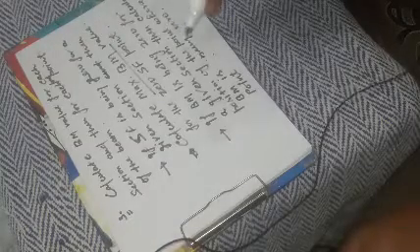This point is also known as point of contraflexion and is also defined as the point at which bending moment curve changes its sign for a given section, right? Change its sign for a given section means 0 will be a reference point. Up to the 0, it will be on positive side, and down to the 0, it will be on negative side.